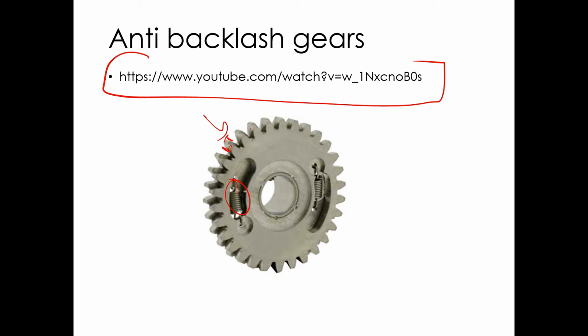They make gears like this that you phase, and then there's bolts that you clamp these things together. Those are better. You're still going to have some backlash, but it's going to be very, very small. So those are probably the best true anti-backlash gears.